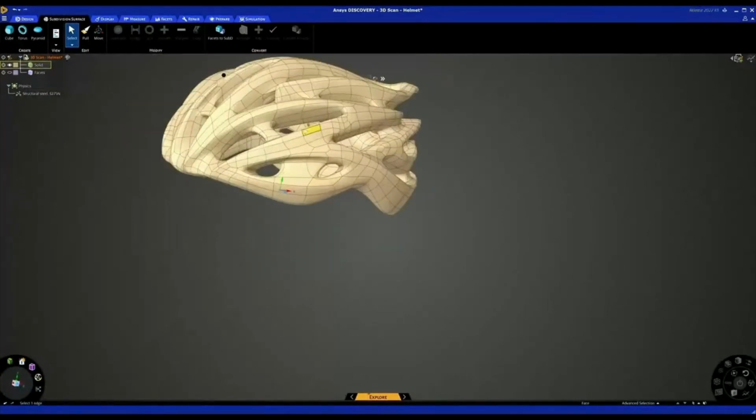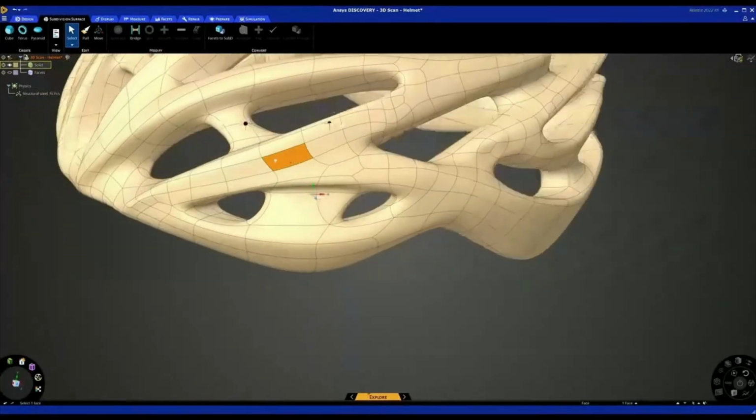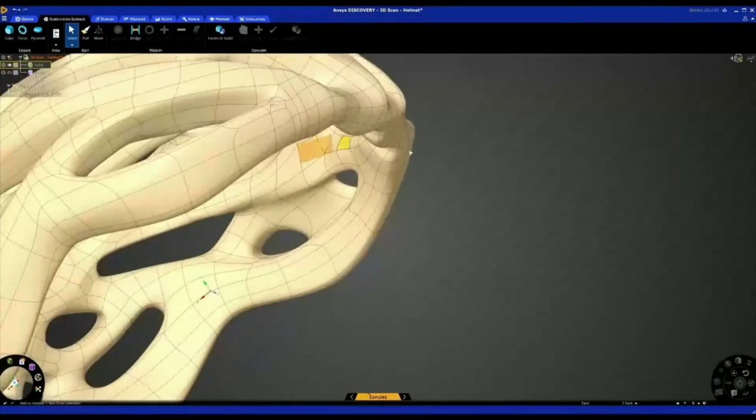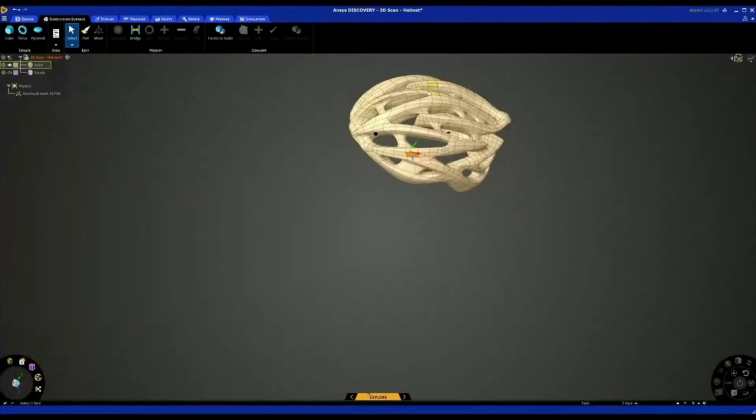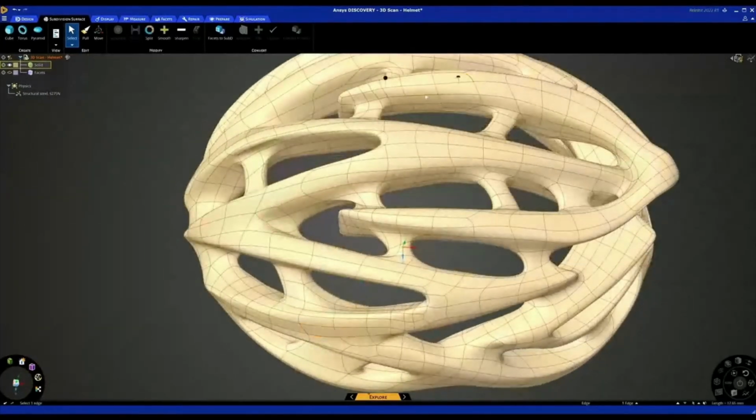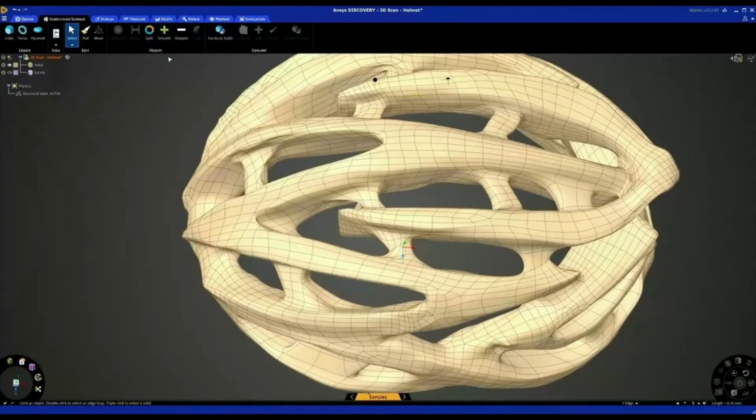So you can create holes in subdivisions by basically doing the same thing where we click the bridge tool and that would punch a hole through if I had two on the other side. So you can do that sort of thing as well. Also, if you actually wanted a bit more control, you might want to actually split the surfaces into numerous more, so it gives you a bit more control.